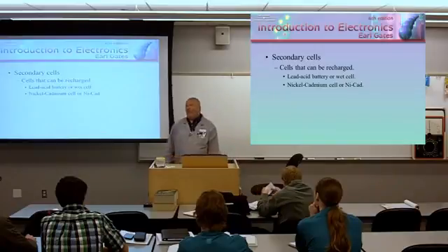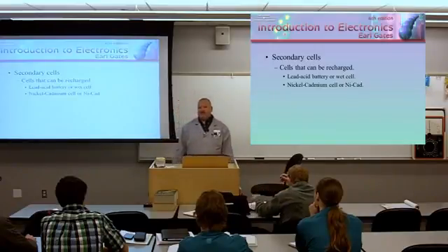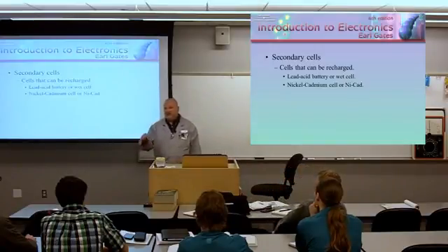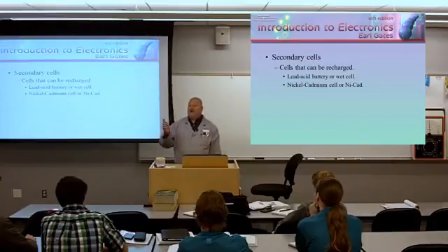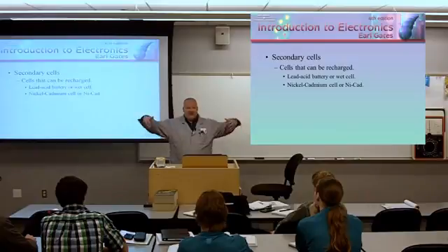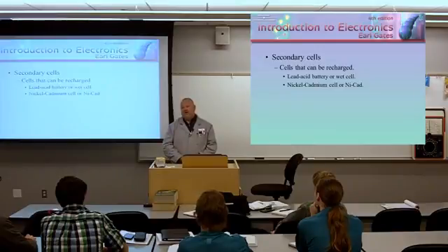So back on the submarine, they were really concerned about that on a daily basis. They sent somebody down in the battery well to take those readings, because if they saw a cell that started to develop an internal short or a problem, conceivably it could take all of that energy and dissipate that energy through that one bad cell. That's bad news. Because, oh, by the way, you know why we had a battery bank?